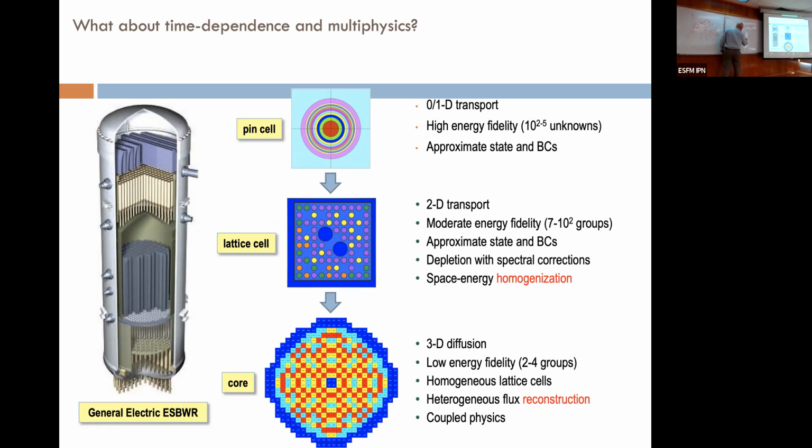then your time step, so we haven't done time discretization yet, but if we did a time-dependent problem, then we would have to break this up into discrete time steps. And you could have big time steps, or you could have small time steps. The smaller the time steps, the more accurate it is. The bigger the time steps, the more error you're introducing. But with fluid flow, if you have cells, let's say we have this one-dimensional cell, and each of these is 1 millimeter, then you don't want your time step so big that the fluid from this cell goes all the way over to this cell in one time step and never touches the cells in between.